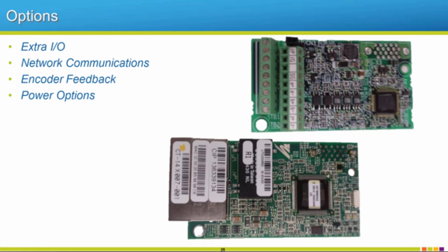But very cool stuff with drives. Just remember, with a drive, you can save a lot of money in a lot of your applications, and you have great control. Even at our lowest control method, you don't have the issue with starting across the line. They've become very cheap, especially the smaller units that rival the cost of a soft start or something like that. So you might as well just get a drive and have that full range available to you.